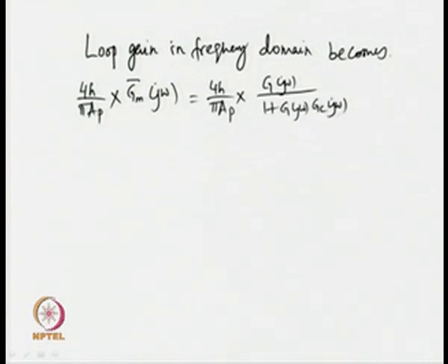And we know that for a limit cycle to occur, for inducing a limit cycle, the loop gain has to be equal to 1, and the phase angle has to be minus 180 degree, which can ultimately be written in the form of minus 1 now.